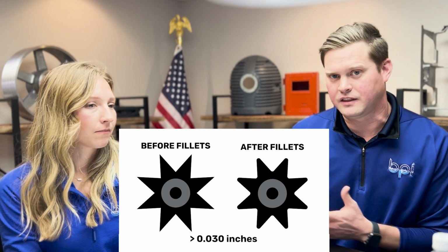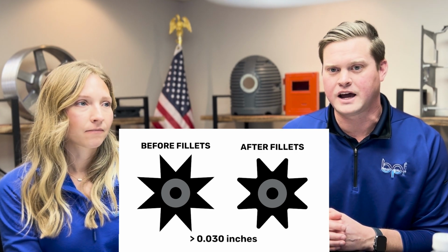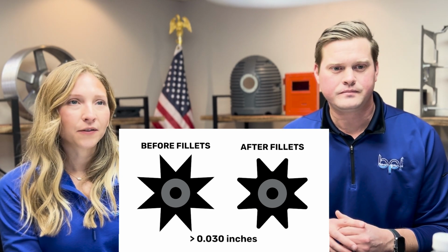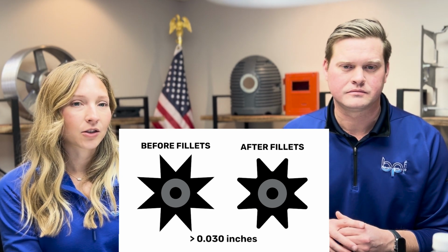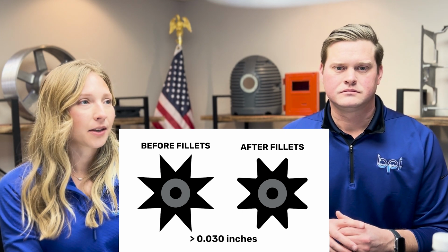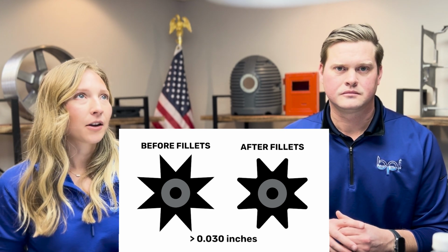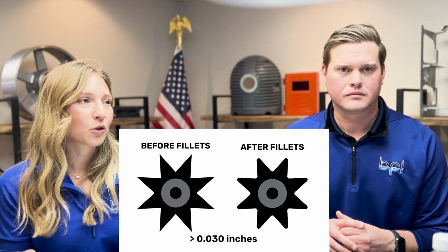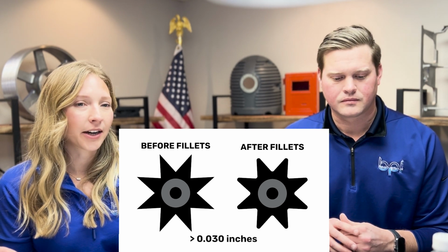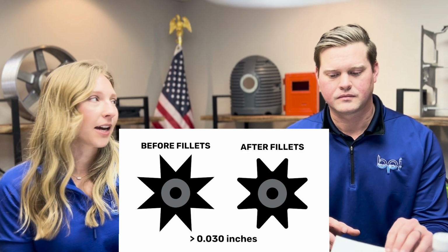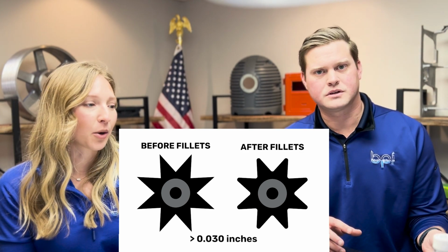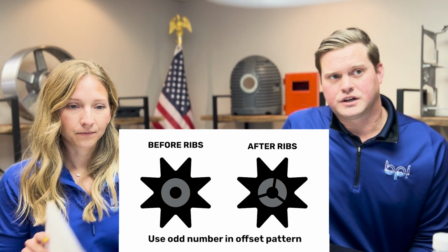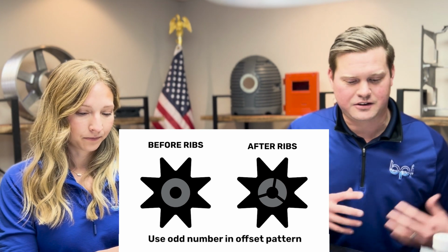So really designing that again up front to make sure that that casting comes out to a good quality standard. Yep. Especially if you're looking at casting that's starting to get larger in size, but you're still maintaining relatively thinner walls compared to the size of the casting. That's going to cool quicker, and you're going to get more tears if you have tighter radii on it, and sharper corners. Absolutely. So similar in nature, but not exactly the same.